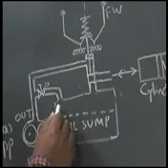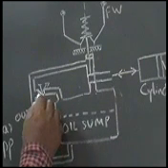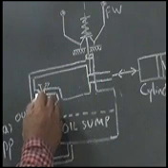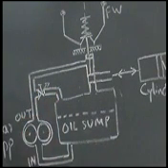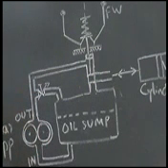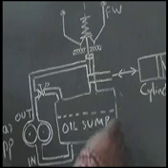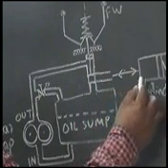So this spring loaded relief valve is connected here, and it is so set that the oil can flow easily to the cylinder, then to this path.